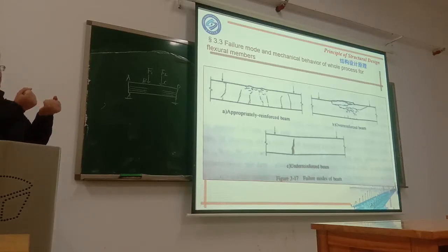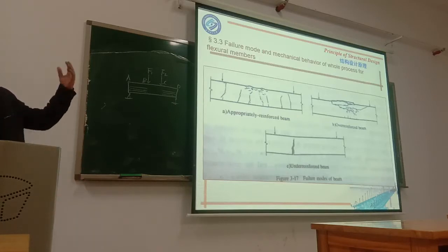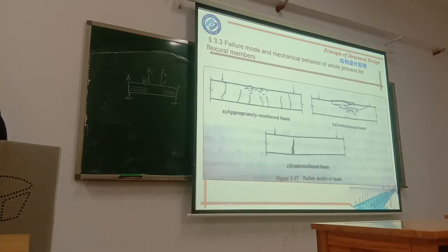The reinforcement can still bear a large load, but the upper part of the concrete has already been crushed. So the function of the steel reinforcement has not been fully used.